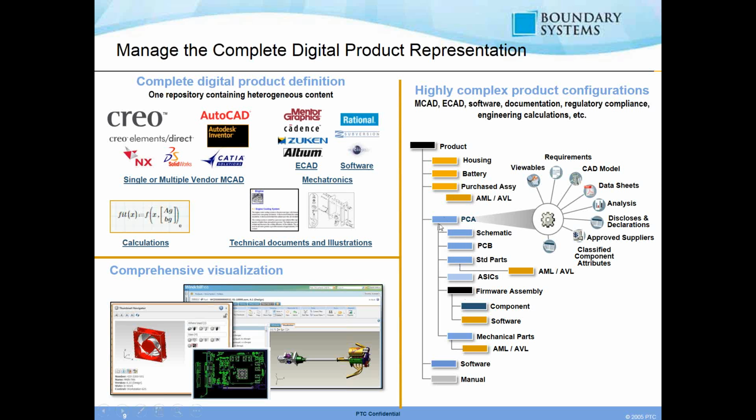And each of these items in our bill of materials is going to be represented by a part object that can be tied to our CAD model, can be tied to data sheets, it can be tied to requirements documents, and so that allows us to build up a full definition of that object. The key is those part objects, the gray gear here, act as those hubs that are the definition of each of the items that are going to go into this BOM or into this product structure, and then we can use the tools available within Windchill PDM Link to manage the structure of those parts.